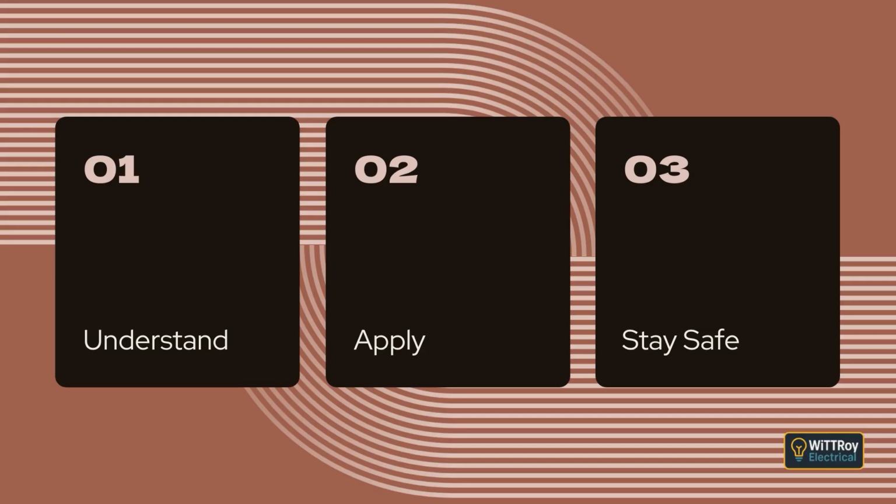Clause 2.3.3.1 General. This clause tells us that every electrical installation must have a main switch located on the main switchboard. If the installation has more than one supply, such as a generator or solar system, each supply must have its own main switch. The main switch must be placed where it can control the whole installation or the part it is meant to protect. Alternative supplies may sometimes be connected in different locations, but only when allowed by other standards.